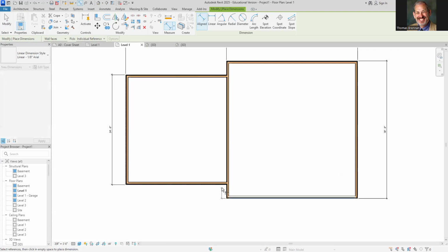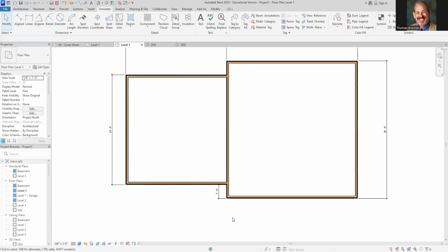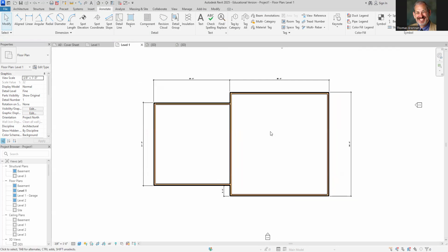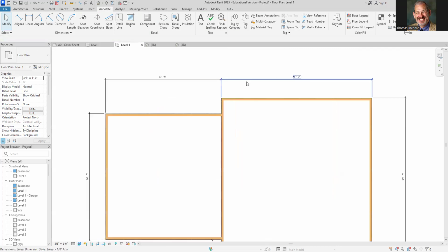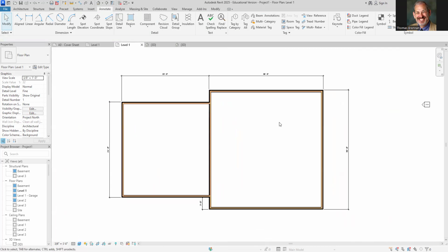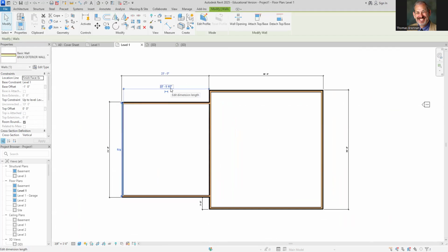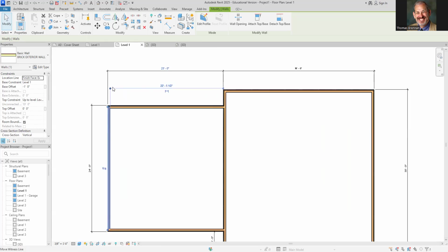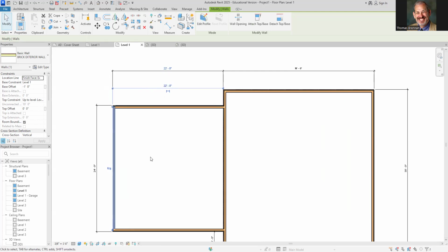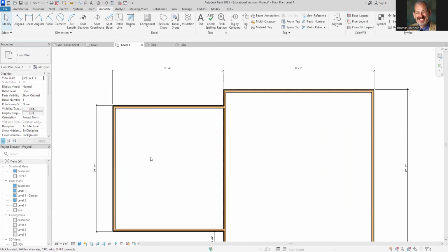Because what you're going to do, you're going to be putting all the dimensions in. And again, there are 2 types of dimensions. There are blue dimensions, which are temporary dimensions, and then there are permanent dimensions. Your temporary dimensions are what lets you edit an object. So to give you an example here, if I click on this where it says 24, I have a temporary dimension here, and you'll notice that it's pointing to the inside. So first thing you do is you adjust your witness lines. You can click on them, and now it's actually measuring that. And let's say I didn't want it to be 23, I want it to be 22. I type in 22, and that does that.